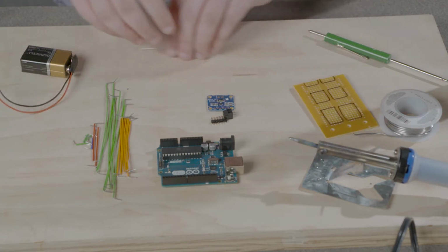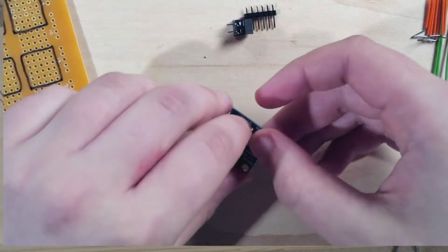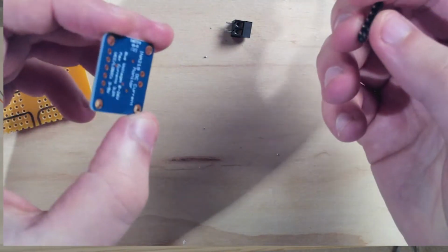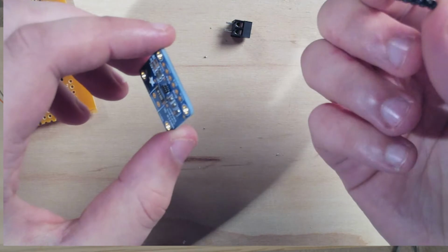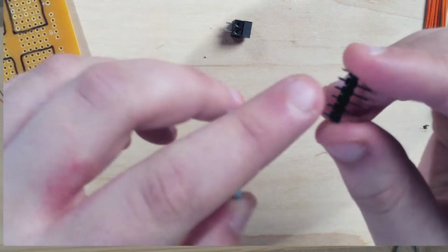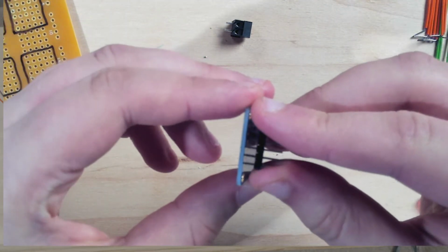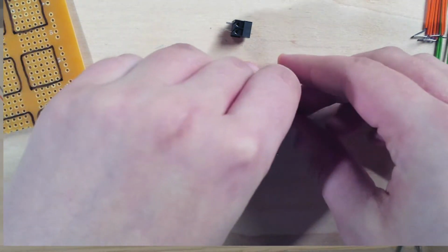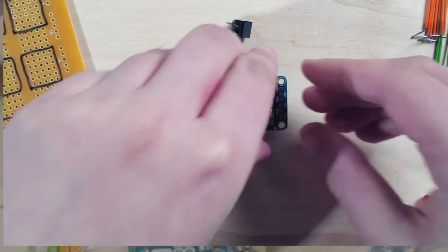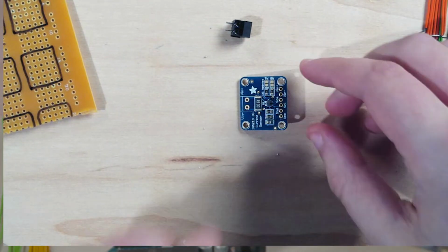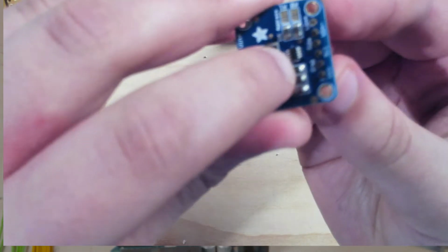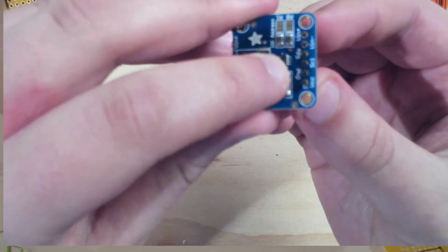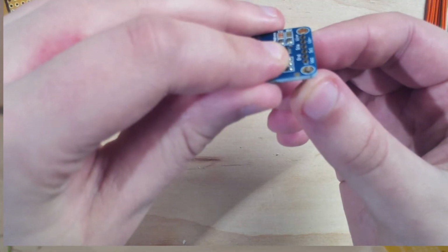So we'll begin by soldering the current sensor together. There's 3 pieces. We're going to take the one with the most prongs, and the smaller the sides, we're going to go through the bottom of the current sensor, and it should look like this. Now, we have to be very careful and solder each one of these and make sure that they don't touch. So let's get started.